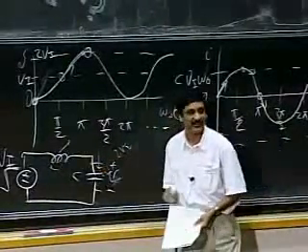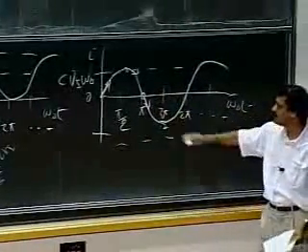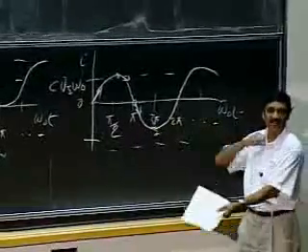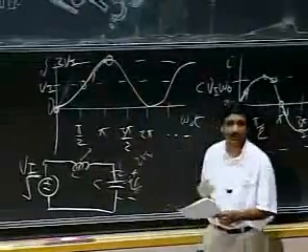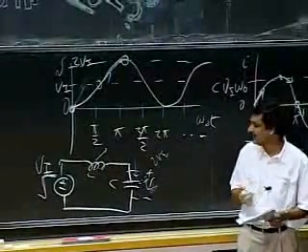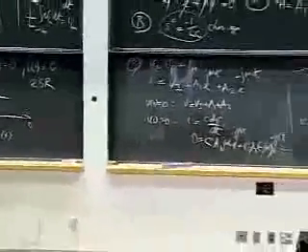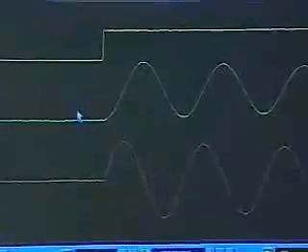So that begins to discharge the capacitor. And then the current goes down to a maximum negative current, and this process continues. So what you're seeing here is energy sloshing back and forth between the two, and that's kind of a key. I'll just quickly put up a demo that you can watch as you're walking out. So for a step input, notice the green is the voltage across the capacitor, and the orange is the current through the capacitor.